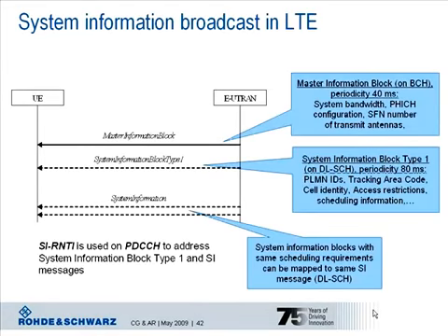The data in the master information block are the only system information which are transmitted via a dedicated control channel, meaning the physical broadcast channel. All other system information is transmitted using the shared channel principle. That is what Christina explained during the explanation of channel mapping in LTE.